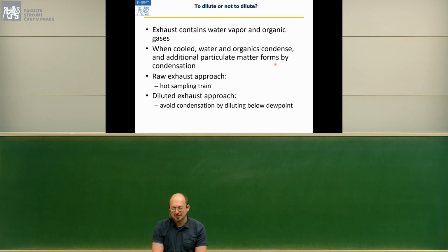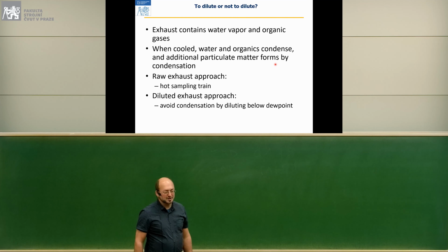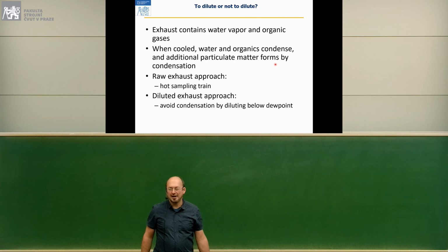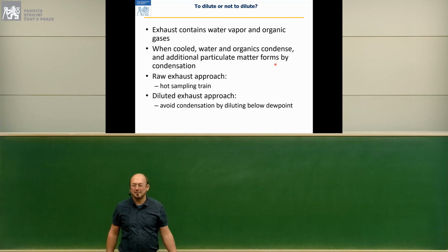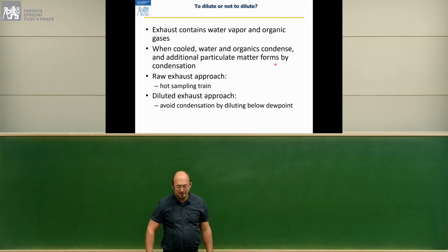If you burn gasoline or diesel fuel, the concentration of water in the exhaust is comparable to the concentration of carbon dioxide, which could be 14% at stoichiometric air-fuel ratio, or several percent, up to about 10%, plus or minus, on diesel engines.